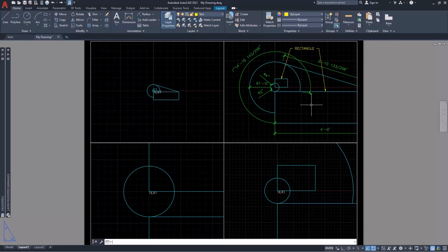Note that we can see bits, parts, and pieces of our geometry in each of the four previously created viewport windows, yet we only see our newly created dimensions and leader in the top right viewport window. The viewport window is scaled to 1 inch equals 1 foot annotation scale. The annotation scale set in model space was current when these annotative objects were created.